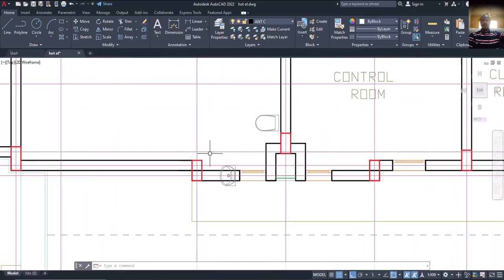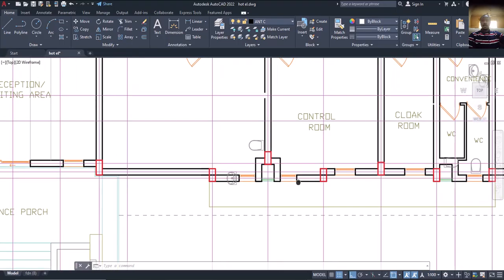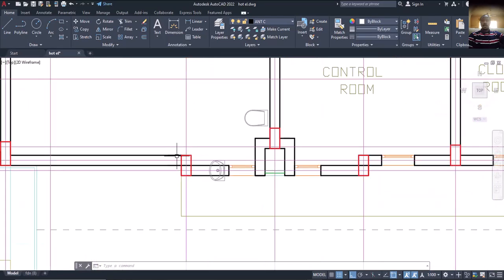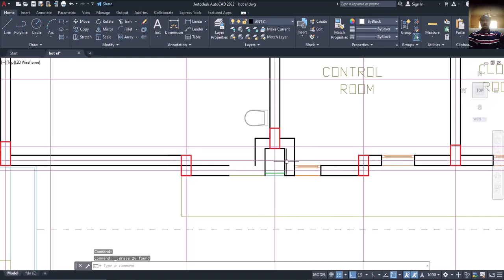Is that okay? That will be formed during construction, because if I say I want to follow this duct, I'm going to have a column here, maybe column here, so that this one can come and rest on this beam, and this one will come like this. That's a lot of columns. Is that okay? So you can use it during construction. We can use slab, and during our detailing, we can bring out this shape here. Is that okay? So that's fine. So I'll remove this one. Is that okay? And remove this one also.